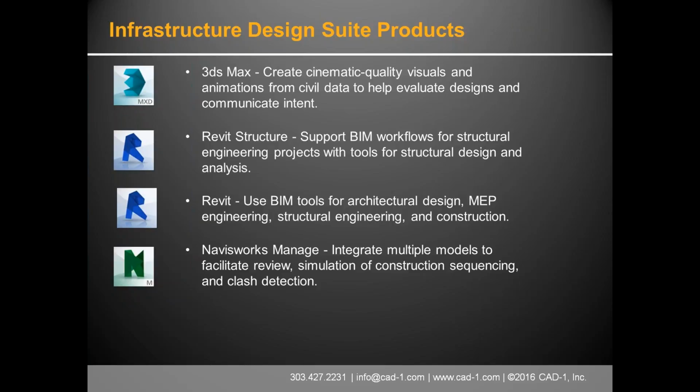A good example would be, we're designing a road, and this road has an overpass that goes over the top of it. Well, my pier has some supporting foundations, but I also have utilities that are in this area. So are these pylons for my piers going to be interfering with or clashing with the existing utilities that I have in the ground? And if they are, where are they and what software is it coming from? Nice thing about Navisworks is it can grab data from all sorts of different software. It doesn't care what the file type is. If it's a modeling software, it can pretty much read the file type and then bring that in and run those clash detections on it.